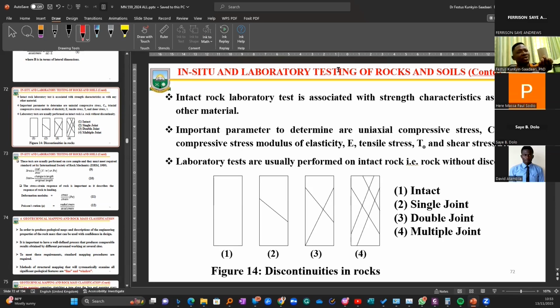And this is going to be a representation of the strength of the rock you have there in your mind. What comes to mind? So it means if I pick any sample that already has failures on them, I will end up testing and getting lower values, which will mean that the rock is not competent enough. And so I have to inform management. If really the mineral we are interested in is of a higher grade we can't do without, then it means they have to provide extra funds for us to provide support. When in natural sense, the rock itself was competent, but because we didn't pick our sample at the right locations.